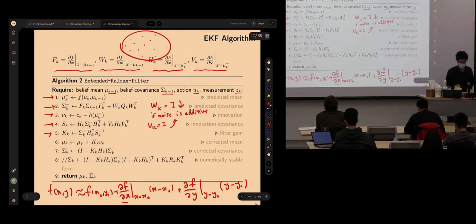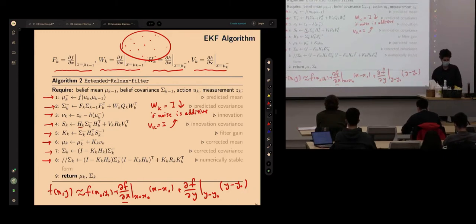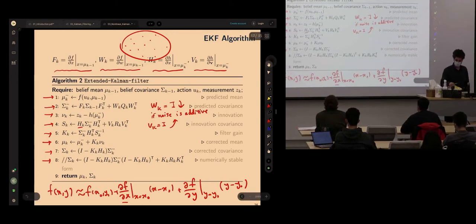So if you have a very good sensor, possibly expensive, maybe with 1 or 2 observations, you can quickly converge. So the linear update rule, updating the covariances, they're all the same. We don't change anything, except H is, again, the linearized model. So that will give us the extended Kalman filter.